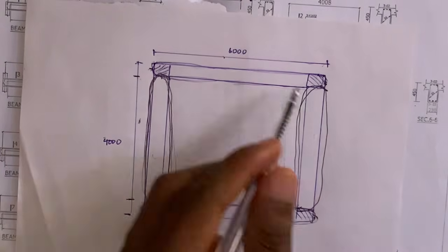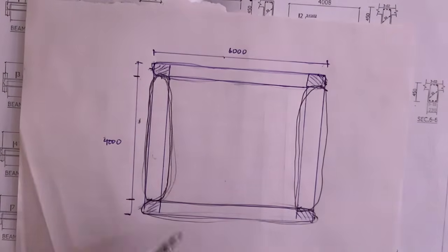So it means that the total perimeter for the beams in this drawing will be 19,080. So now you would convert this to meters, right? And then multiply it by the width and the thickness of the beam, as we've already discussed. So that is the process you go about measuring your beams.